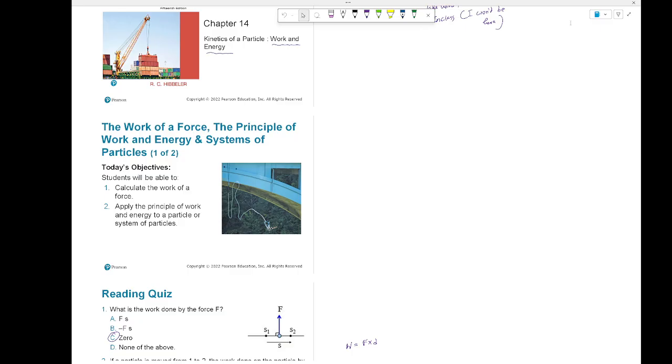Understand, Joe? And in the second problem, we do have this force with an angle. It's kind of going towards the ground or wherever this is moving, right? So that means obviously it has two components. One is the tangential component and another is the normal component, right? Along the normal component, the particle is not moving. Where is the particle moving? Do you know? Along the tangential component, right?